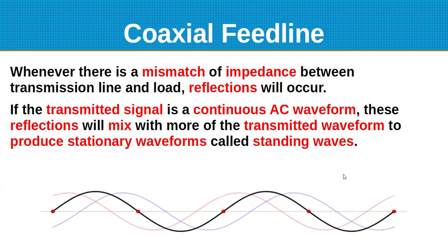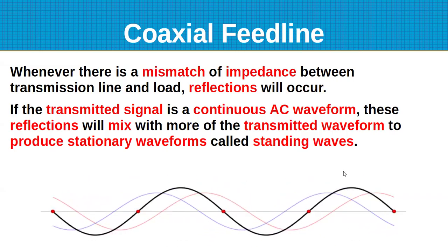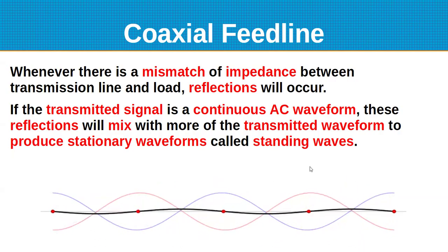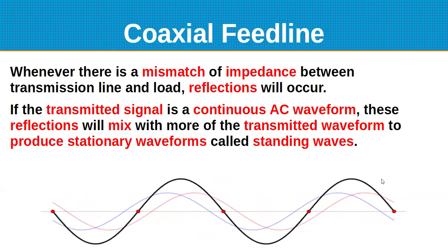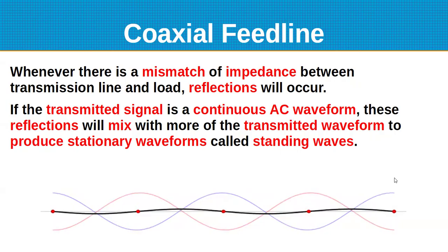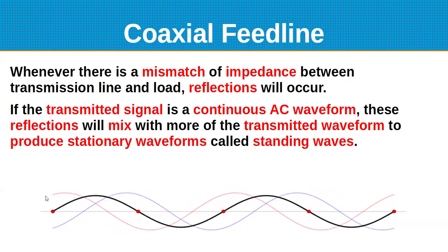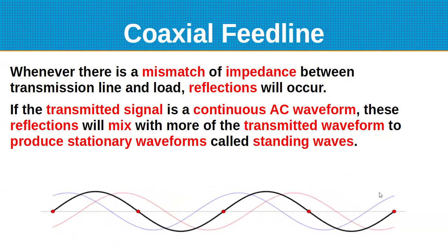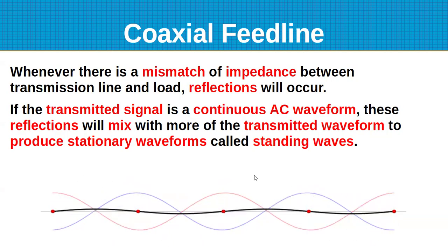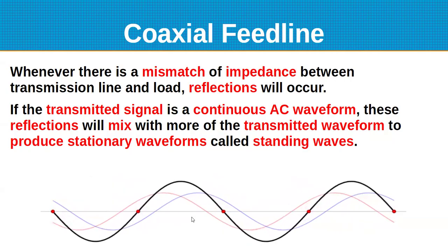So does that create a hum or a feedback when it does that? Well, indirectly, what it does is it causes the reflected signal to come back on the outside of the shield of the coax, or as common mode on the parallel line, which will come into your shack and it's radiating.